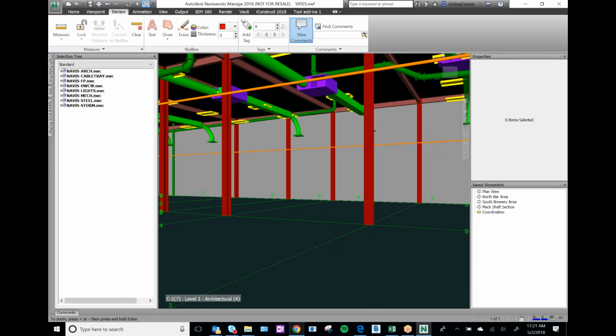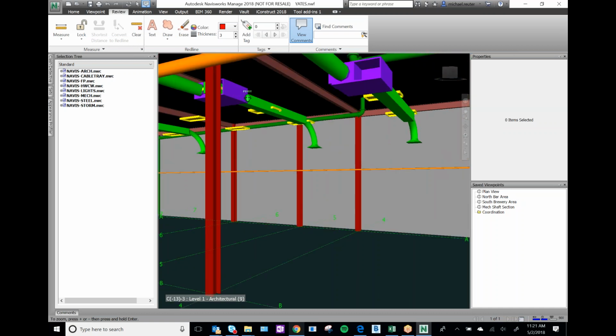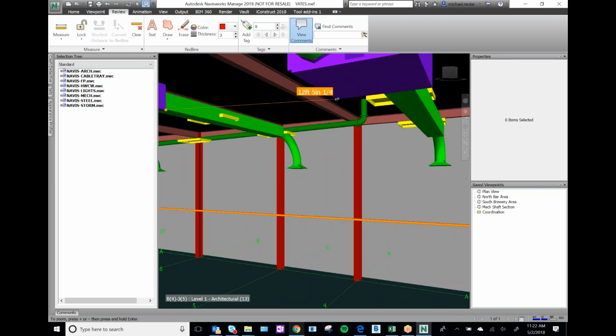Okay, let's just see here. I'm going to click From. Let me zoom in here. I'll click from one corner of this. When I roll over this, you can see that I'm picking a surface here. It shows me exactly which surface I'm on. If I click an actual corner, you can see this little asterisk come up, right? So I click on that. Then I can click on, let's just say this one right here, just for simplicity's sake.